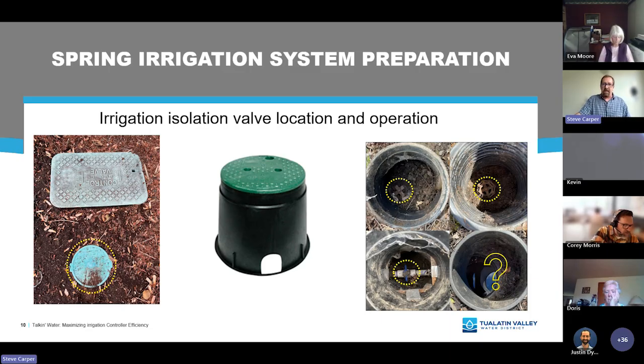Then you're either going to have the cross-top valve or a ball valve. Sometimes they can be PVC, but that configuration is the same. Again, perpendicular handle, valve is closed, parallel, it's open. Or you may have a gate valve, which has that spigot handle. And sometimes you may have valve boxes that have indeterminate devices down there.